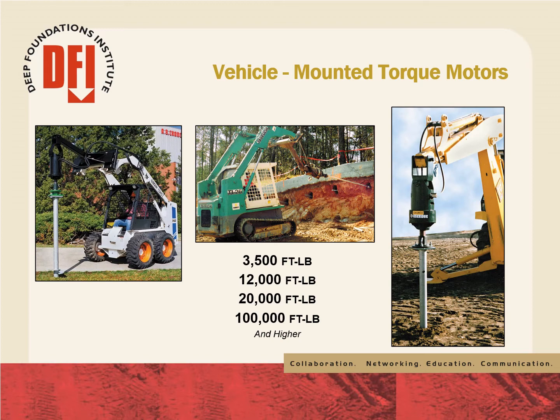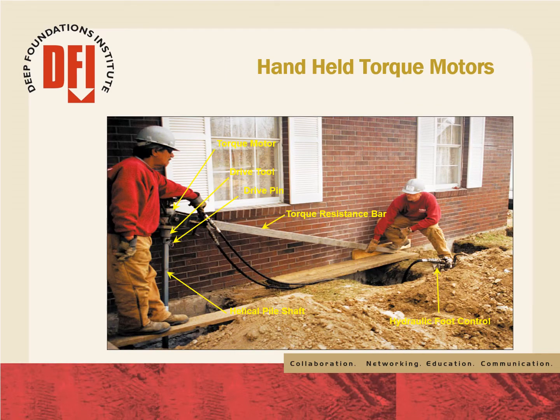Helical piles are typically installed with machine-mounted hydraulic torque motors. The machines can be front-end skid steer loaders, mini excavators, rubber-tired backhoes, and large track hoe excavators. Helical piles can also be installed with portable hydraulic torque motors, which keep mobilization costs down and minimize site disturbance. Portable installation equipment makes it possible to install helical piles in very tight access locations.